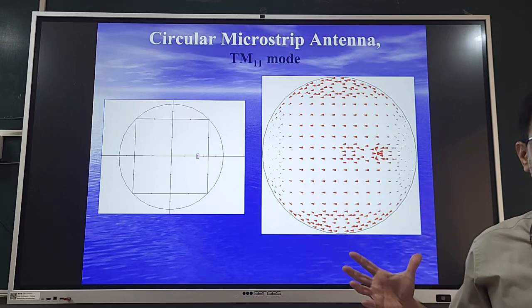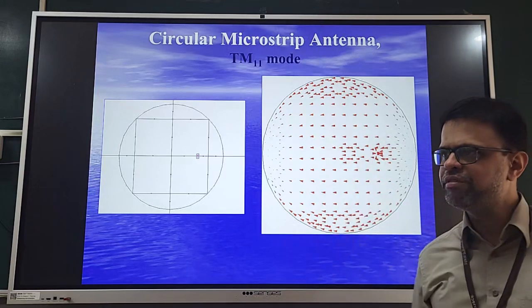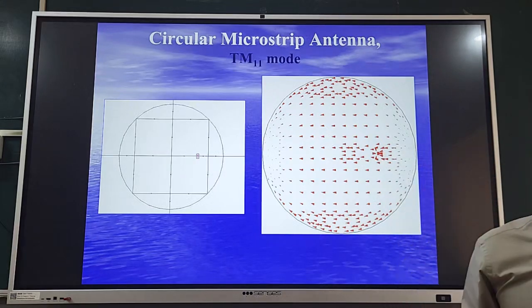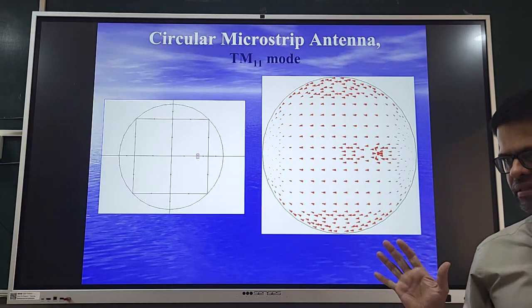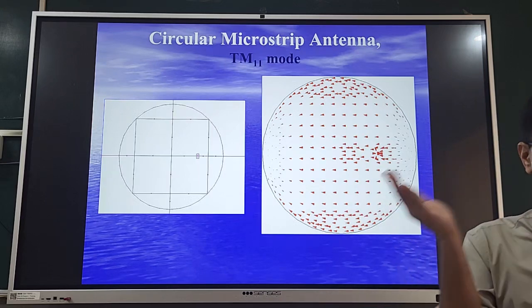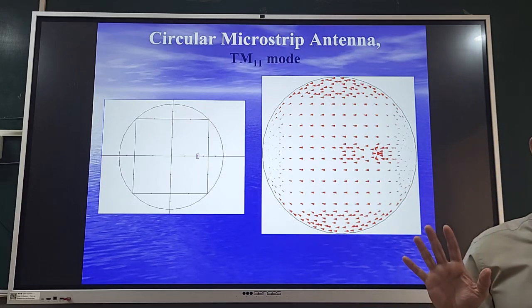Otherwise, generally for a 50 ohm matching on FR4 substrate, the value of X is taken around a/2, where a is the patch radius. Around a/2 it works on FR4. On other substrates it varies as the loss tangent varies.